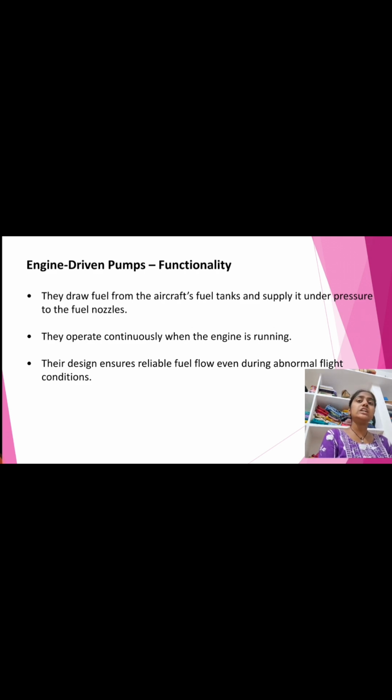One of the key challenges in fuel pump operation is preventing cavitation, which occurs when vapor bubbles form in the fuel due to low pressure. Cavitation can cause damage to pump components and reduce efficiency. Boost pumps play a crucial role in preventing this phenomenon by maintaining positive pressure in the fuel lines.